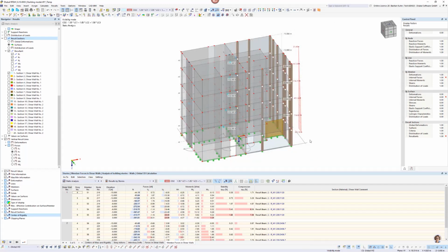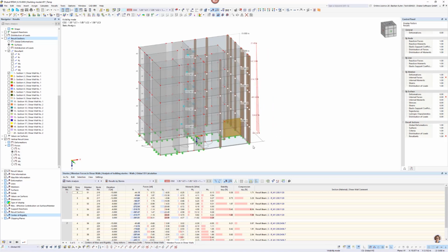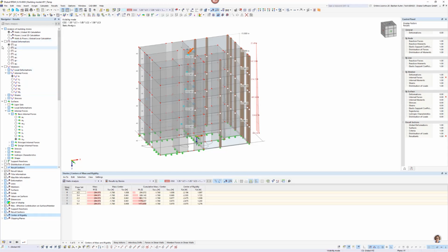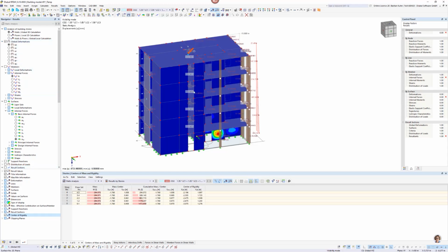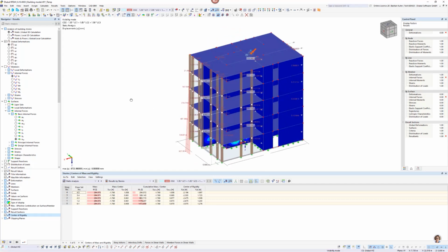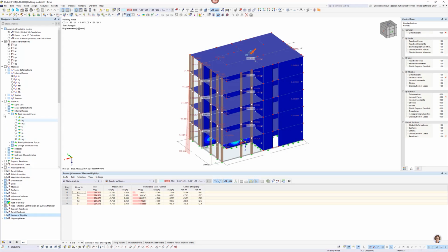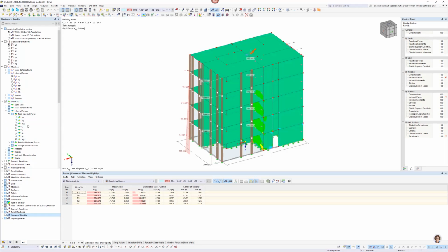All right, maybe we can also get rid of the grid on it. So, okay, then you get this information and also this information in here. This is all important for the walls. I will activate the global deformation in here. We have this little local point in there, but that's not so important. And here I have my shear forces inside, that is the important information I'm receiving from this. And that's the information of the walls.